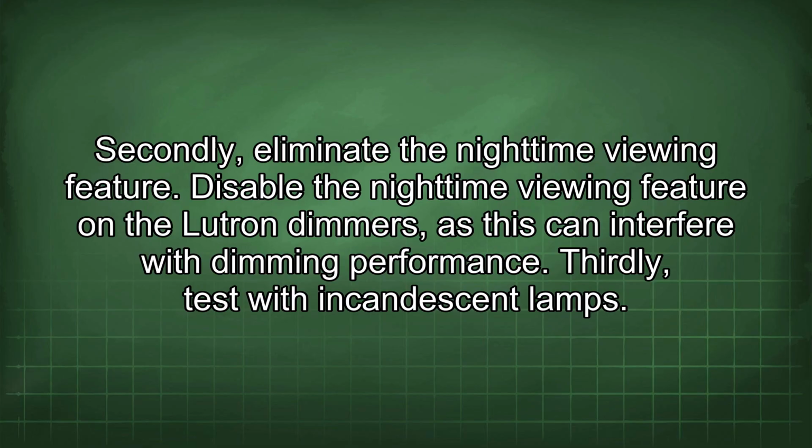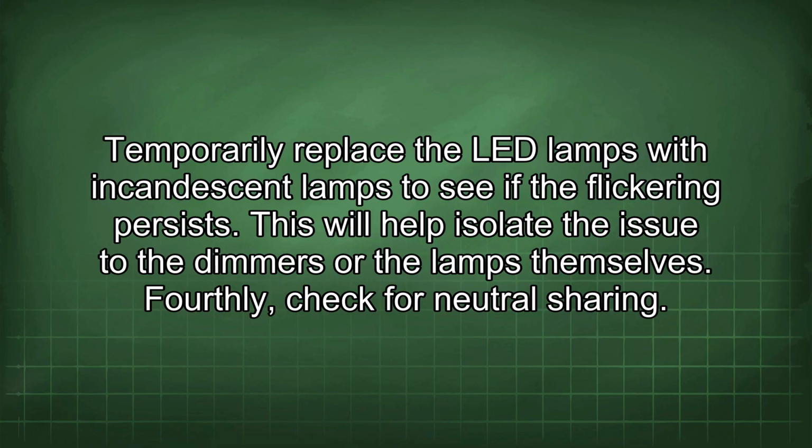Thirdly, test with incandescent lamps. Temporarily replace the LED lamps with incandescent lamps to see if the flickering persists. This will help isolate the issue to the dimmers or the lamps themselves.